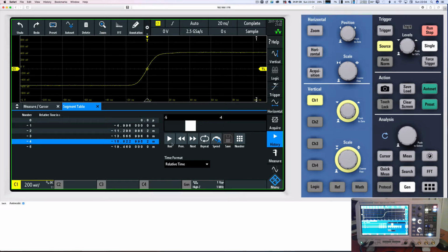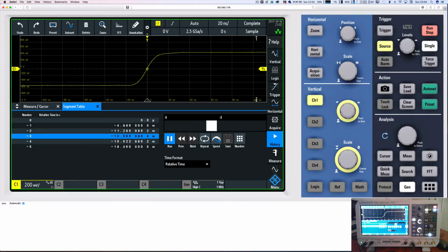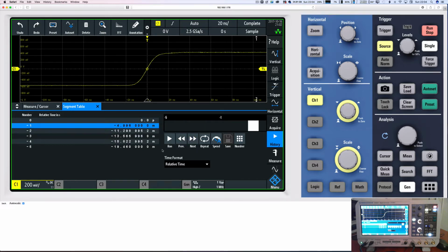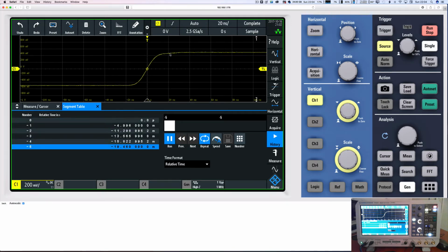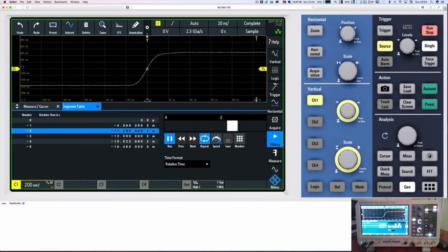In actual fact, over here we can actually play that, and this is a similar sort of thing to the Rigol, which has a sort of history mode but has a physical dial for that. But this is quite powerful actually once you get used to it, particularly with decodes. If we want to put repeat on, put the run, and that's now running through all my waveforms, but you can only just see this changing, because this waveform was pretty constant.